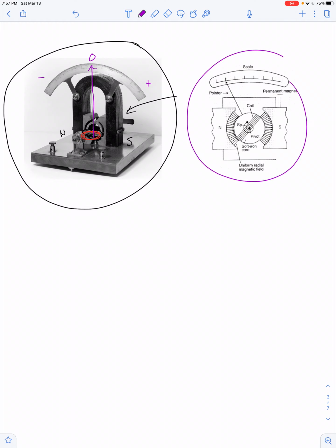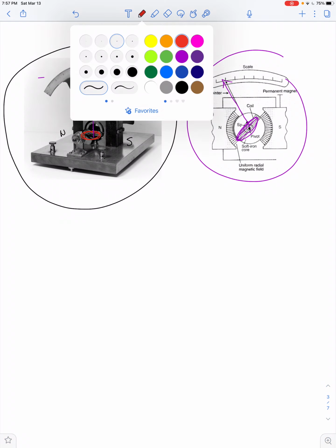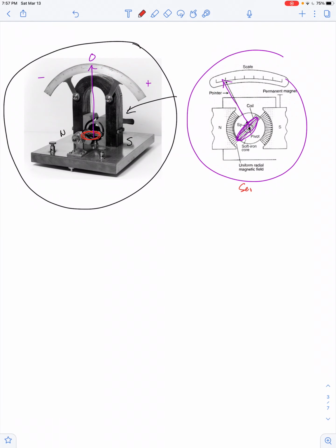Here's a schematic diagram of that whole thing. Again, there's our loop of wire. There's the needle that goes along the numerical scale. What we don't see is whether the other resistor is connected in series or connected in parallel. So if the other internal resistance was connected in, let's say, series with the resistance of this loop of wire, we might say there's some additional internal resistance plus the resistance of the galvanometer itself. And then in that case, that's how we would construct a voltmeter.